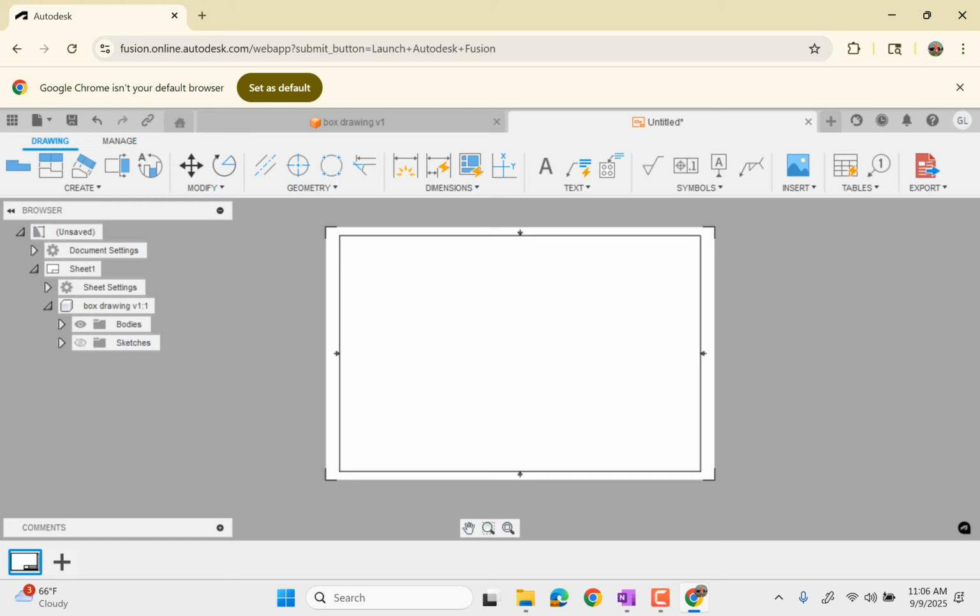And what we're going to want to have is 3 perpendicular views normally. I mean, sometimes you don't need that if it's a very symmetrical shape like a disc or something. But we're going to have 3 perpendicular views that allow us to show the dimensions of different features on the part. And then down here, I'm going to put a sort of 3D angled picture of what it is, just because on these three, I'm going to have kind of like a wireframe view where you can see through it and see the different sides and stuff.